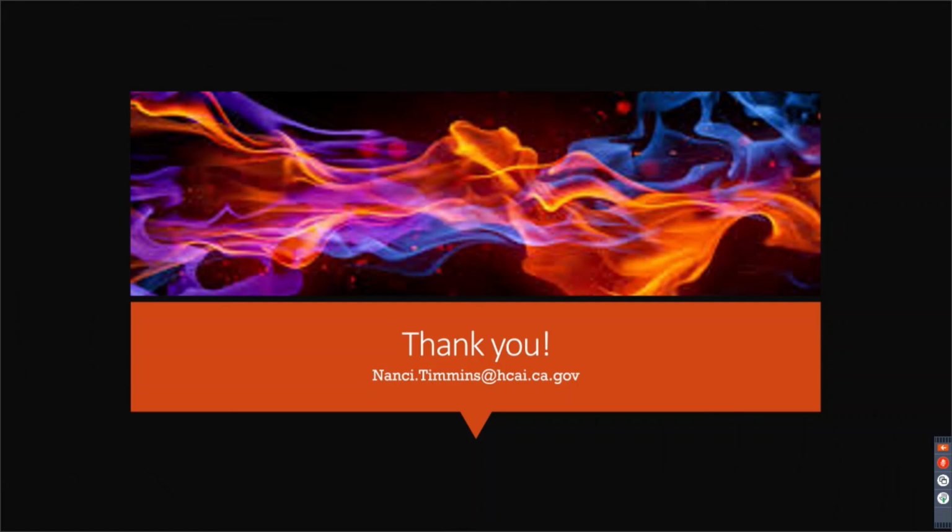Great question, because that's what we really focus on, our timing. And in I-2s, it takes a lot of time to relocate people. And yes, there are provisions for the different construction types that come into play based on timing for evacuation, or in our case, relocation. However, remember the firefighters. The firefighters are going to be here fighting this fire, and if the wall's crumbling on them, we don't want to kill a bunch of firefighters. So it's not just the occupants of the building, it's also firefighters, as well as protecting the adjacent building. So yes, the intent is that wall stays standing for the time that table says it needs to.